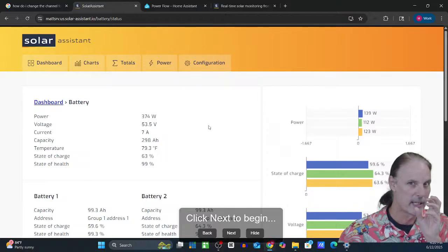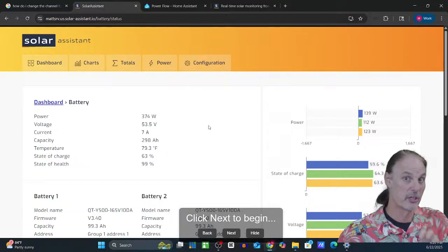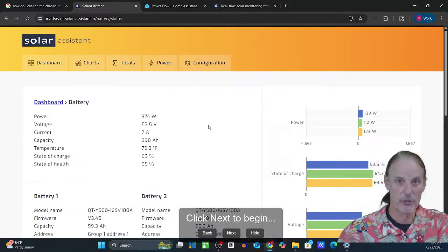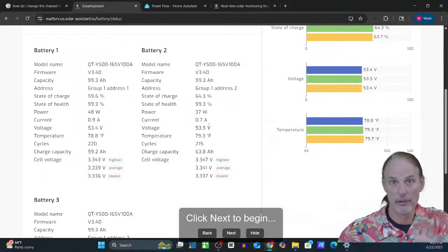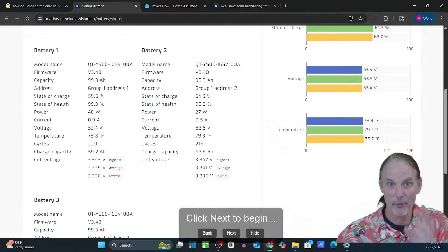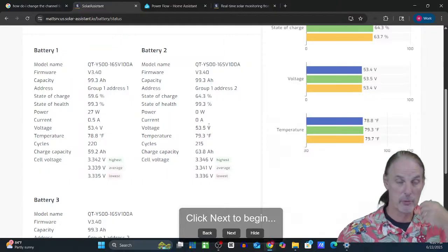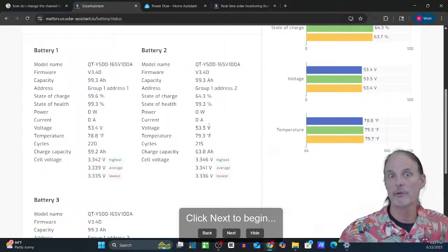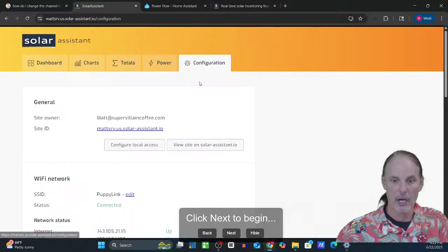If you had told it to use what the inverter reports for the batteries and state of charge, whatever the inverters report will show up here. I have seen on some of the newer inverters that all of your battery information shows up here and it all works just fine. Unfortunately, I have LifePower4 batteries, version 1s, and mine do not show up here. If you have the EG4 wall mount batteries and an EG4 inverter, they do show up. So a lot of that depends on the version.